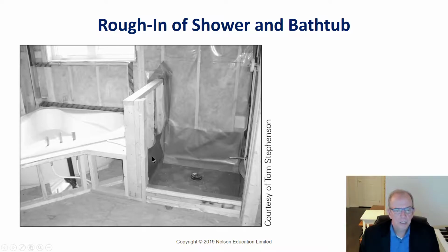So you got to make sure that this pan is protected until the dry concrete is put in, concrete base, and then the ceramic tile is put on, and now it's going to be protected. And of course, this goes up. There's going to be a substrate that's going to go over top of this, probably a cement board or one of the other manufactured type substrates that are waterproof. Not to use a water-resistant drywall. That won't last. It's been done before. It's awful. But you have to use a proper substrate here.